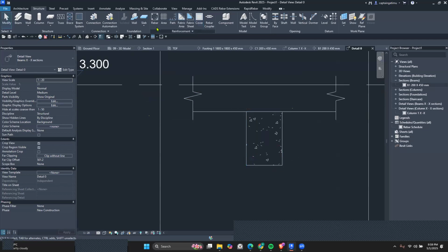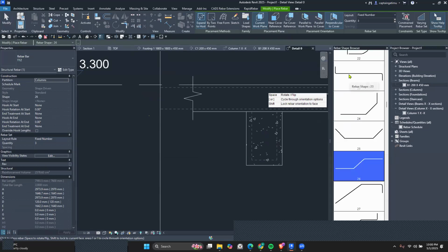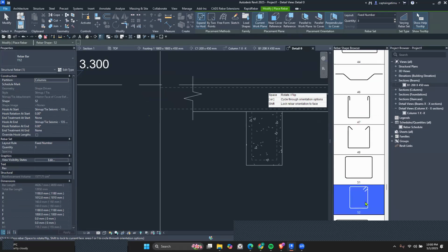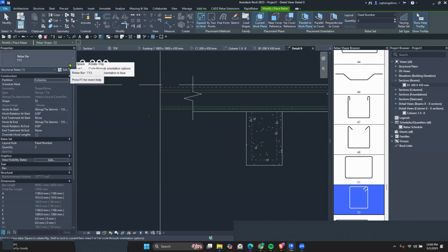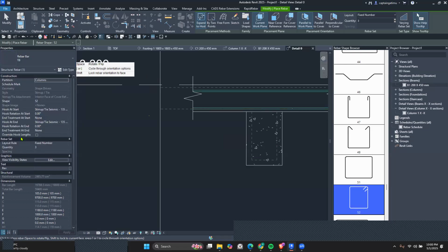So with that, we'll now go to Rebar. Our first step is to select the shape that you want. So you're going to select shape number 52. All right. And for this one, we want it to be parallel to work plane. But before we place it, we are going to do what we have been doing before. Select the ideal size and then partition it. So we said partition is where the bar will be hosted. So this bar will be hosted in the beams. So you can have a partition for that.